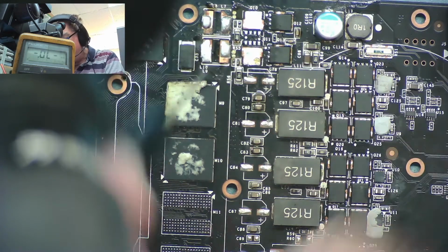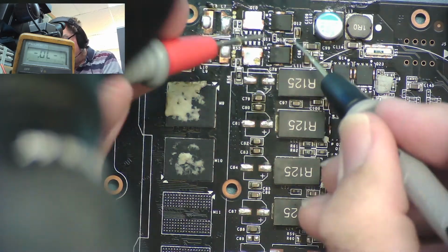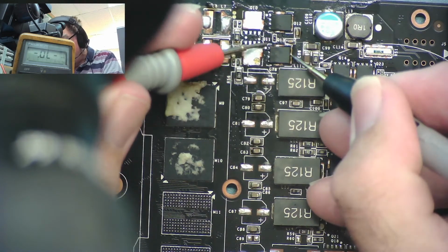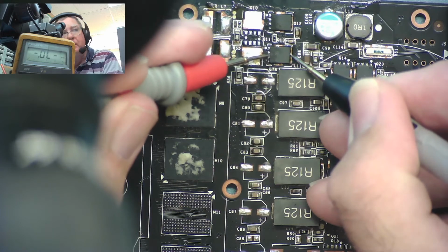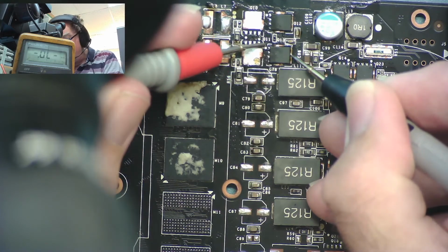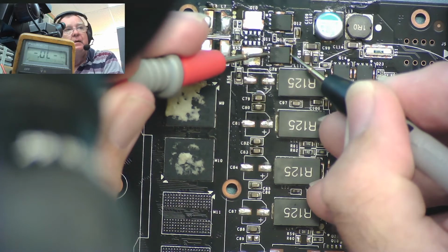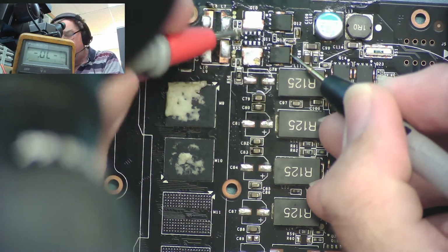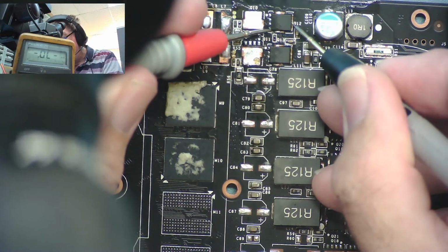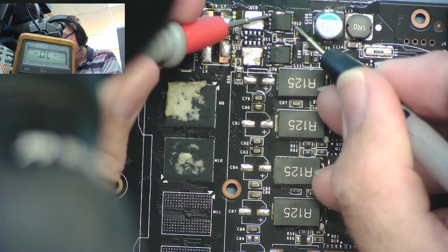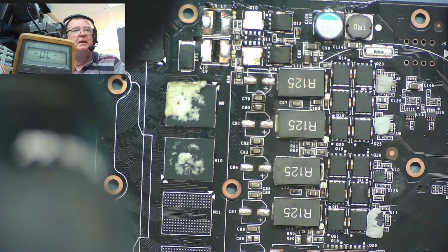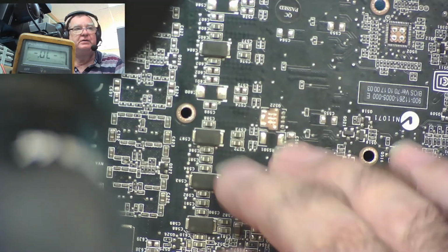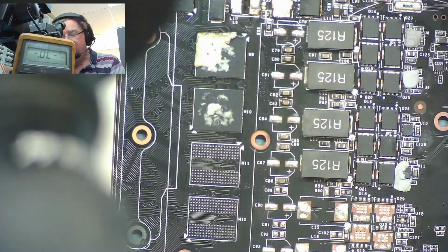Now let's try find the gate, which I'm guessing is going to be one of the end ones. Let's try this one first. Touch the gate. Nothing happens. Try the other one. No, so either I can't test them in the circuit or it doesn't work. I did wonder if it was possible once the driver chip has been disconnected, which it isn't. It's still there, by the way. Yeah, that's not going to work, because this is still acting as a low resistance. Let's take them off the board and see if they are good or bad.